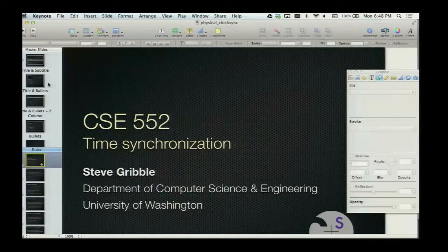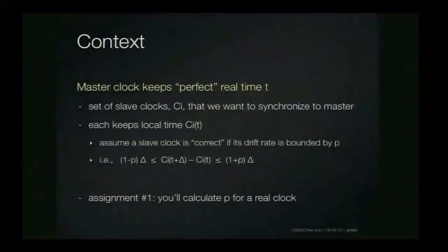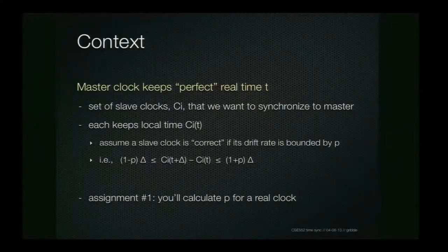You control the temperature of the oscillator so that it'll in some sense be stable. Now you just need an accurate thermometer, which is a whole other discussion, but somewhat easier to pull off. I believe it. Well, actually, more in the sense that if you can get it consistent, you can tune these things, because it's easier to measure the frequency than it is to get it right, so you can tune the circuit. I see.